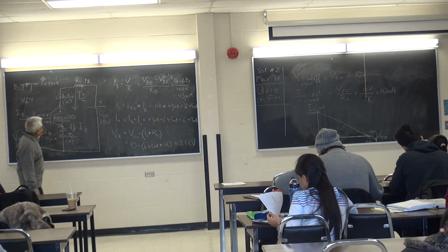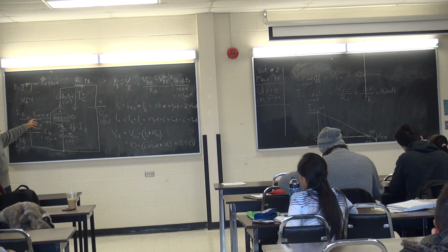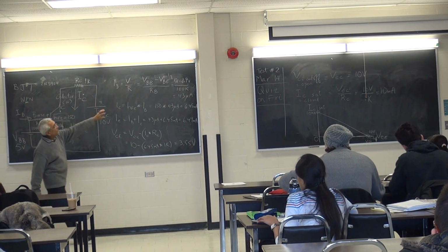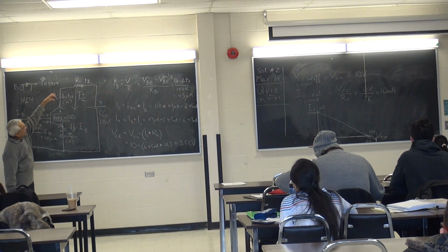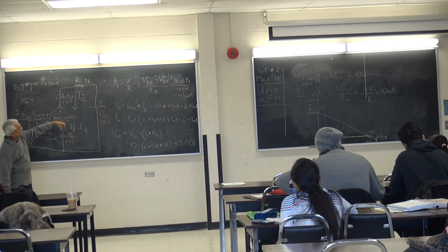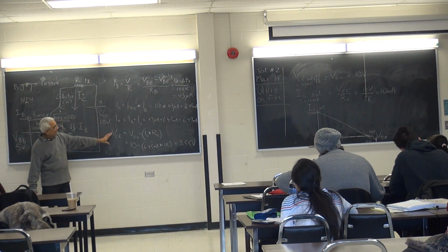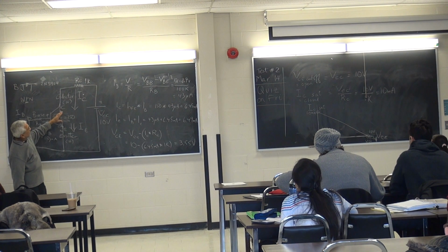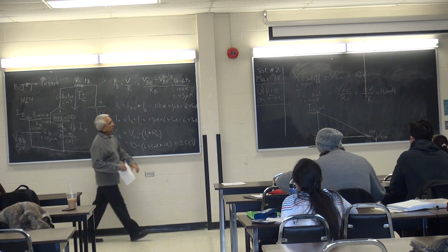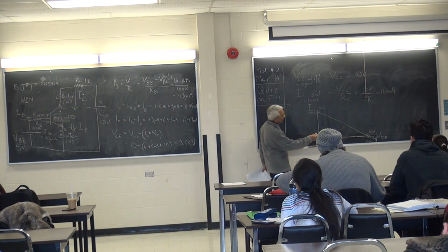Now on that circuit, I'm applying a little bit of base current. How much? 43 microamps. That's causing 6.45 milliamps of current to flow this way, which is causing a voltage of 3.55 volts at the transistor. So it's not 0, it's not 10, but it's 3.55. So where do I show the 3.55?